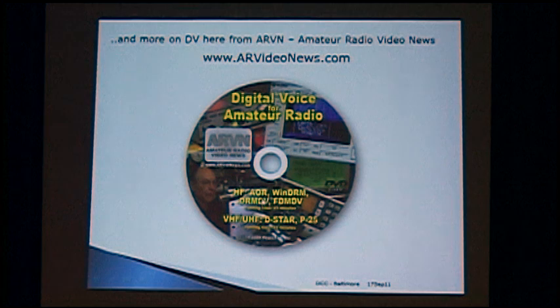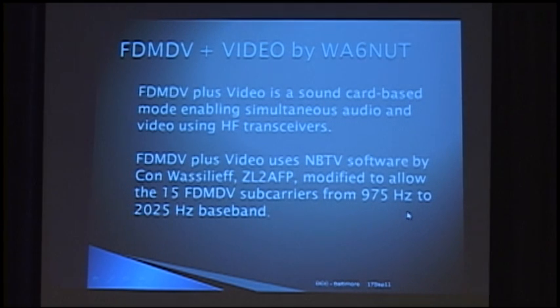And DRM-DV was another mode, although it's not being used now, that was digital voice only. I'll show you a sample of that though. That used the MELP codec and also on D-Star. So I'm just going to speak a few minutes here about this new mode by WA6NUT. It's called FDM-DV Plus. It's a sound card-based mode which enables simultaneous audio and video using HF transceivers. It uses narrowband TV software by ZL2AFP, which is modified to allow 15 FDM-DV subcarriers from 975 to 2025 in the baseband.